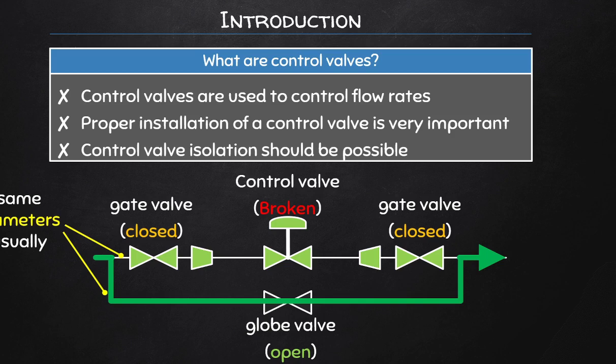closed, so not a lot of the gate was exposed, and it's like a steel flat plate, and the flat plate got eroded. There were issues with the process where they needed to stop the process by isolating the reactor. Unfortunately, the gate valves that closed did not close completely. The catalyst was actually used to block the vapors from coming through, but the catalyst just kept on running past the gate valve because there was a leak.